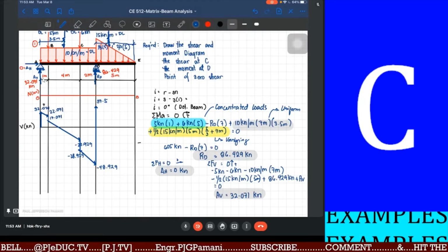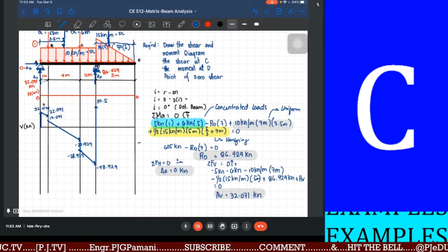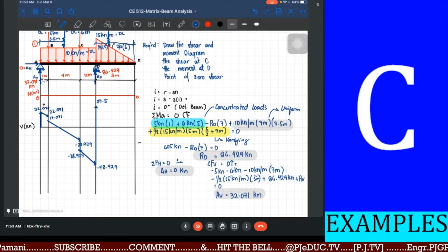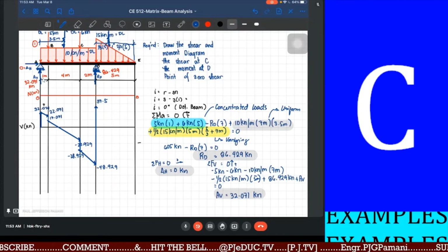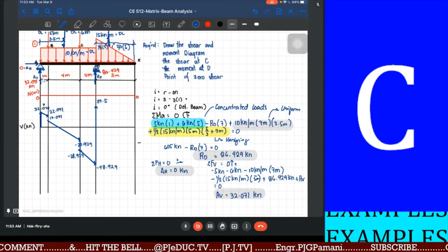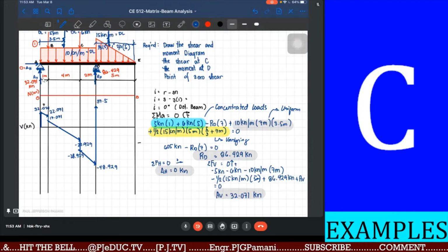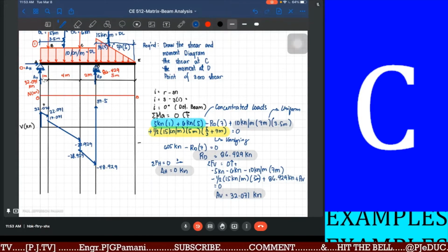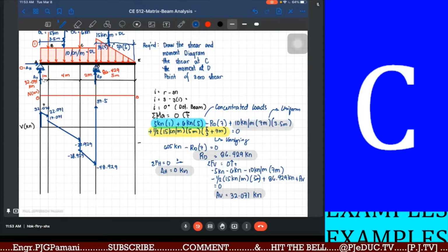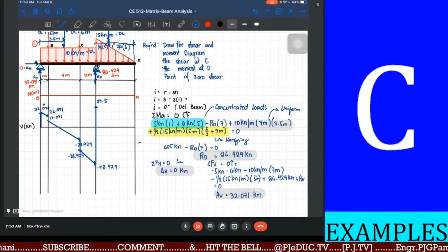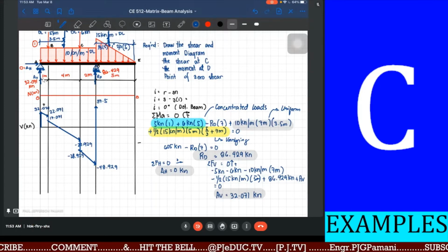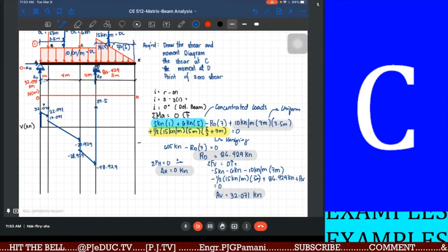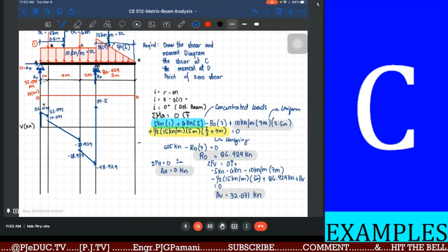Okay? So first degree, 37.5 minus the area of the varying load, which is a triangle, minus 1/2 of 15 times 5, 1/2 base times height. Basically ends at 0, which tells us that our shear diagram or the reaction that we have recently computed are correct. Lumabas ba na 0? Nakuha nyo yung 0?